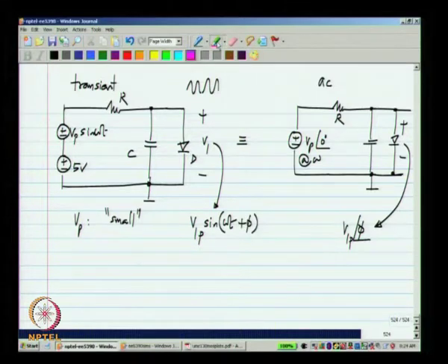So, a transient analysis with a sinusoidal input and a very small amplitude will give you the same result as AC analysis. Now, the AC analysis is by definition linear. So, that will correspond to what happens with a very small input signal. Now, these are all things that you can try out, especially when you are beginning to use a simulator, just so that you get used to what different analyses do and also how to do the analysis themselves.